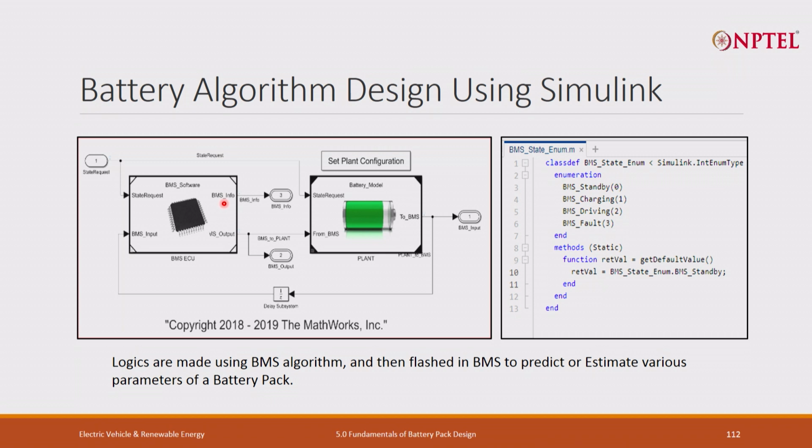You can also use the hardware in loop simulator without even putting it into the BMS, and check all other functionality. So the chances of error in your actual prototype become minimum, and it also gives you a nice overview of how your logic, programs and algorithm are working.